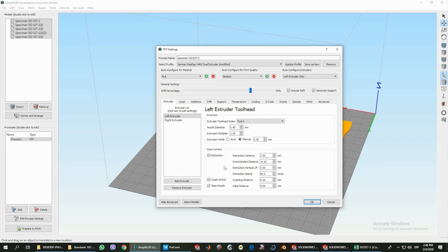What does retraction mean? It's when material is extruded, the rollers push just a little back material, it pushes back the material just for that particular case when you expect oozing of material. You don't want extra dropping on the printed model, which will cause failure. So these are the standard values for PLA material.